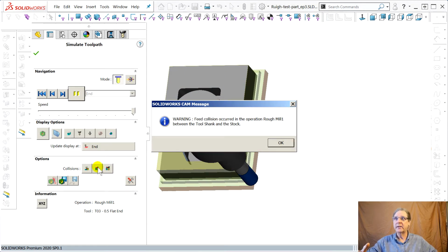See, this is why you click all these buttons before you send it to the mill. You have to click the first button. The tricky thing is if you forget to put the facing in the right order, like I had it once, it'll be crashing those center drills right down through the stock. So that has to be on as you work.